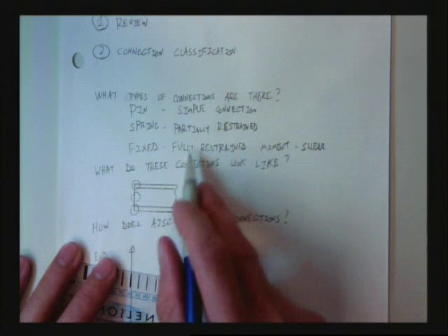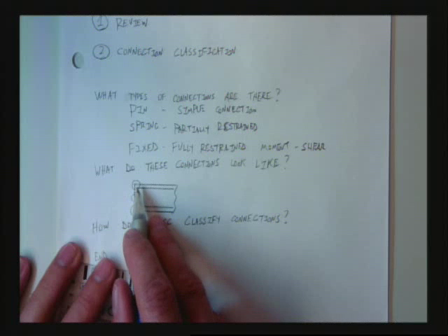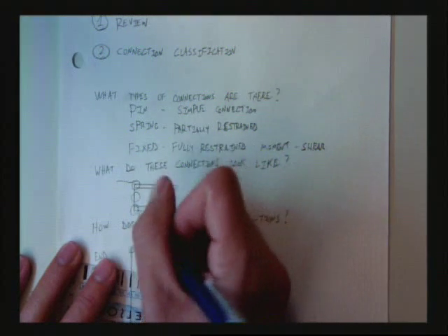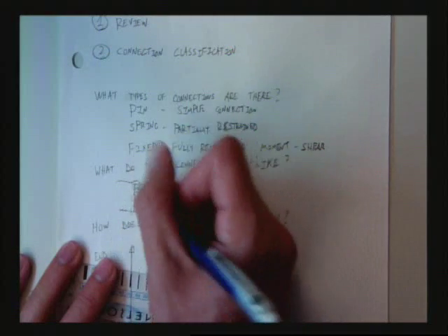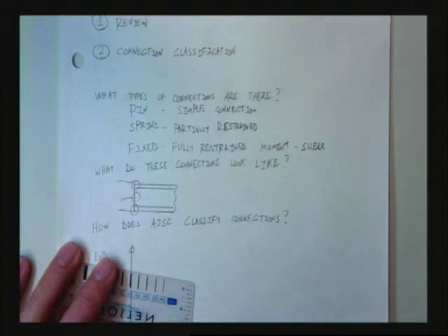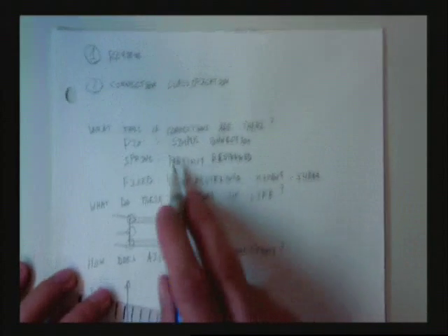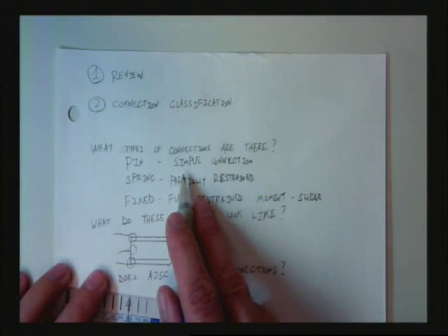So a fixed connection has to provide a load path, at least conventionally, the way we've thought about it in the past, from the top flange to something else, from the bottom flange to something else, and from the web to something else, right? That's what we usually think of. And when we think of a pin connection, what loads do we think of being transferred?